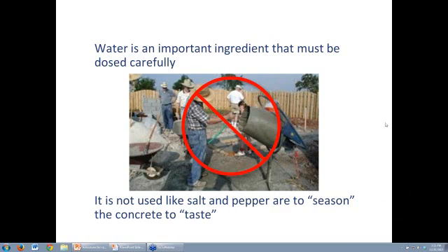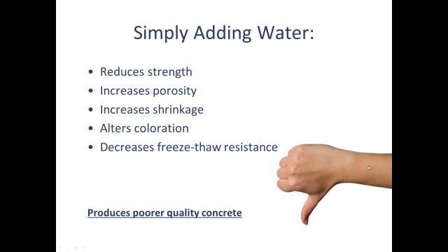Like when I teach my students to make concrete countertops, you never, ever, ever, ever do what's shown in this picture, is just add water arbitrarily by eye and judge the consistency based on some food-related item like oatmeal or whatever. It's super important not to do that, and I'm going to touch on why.